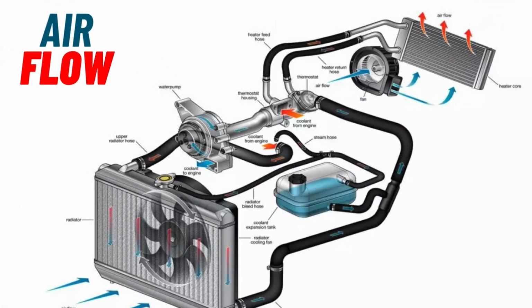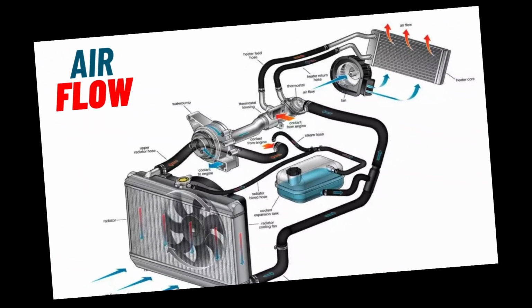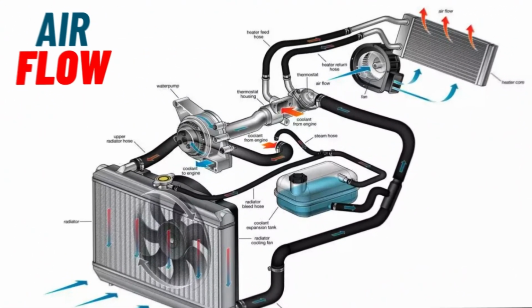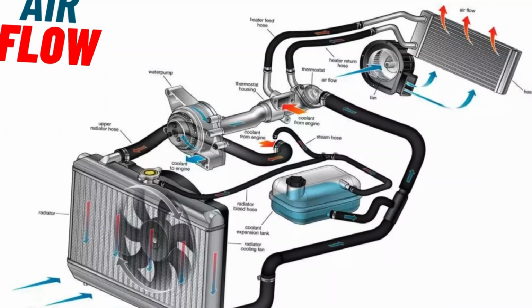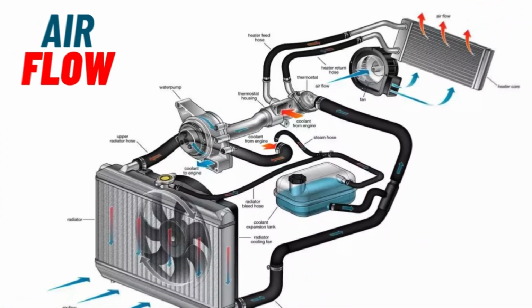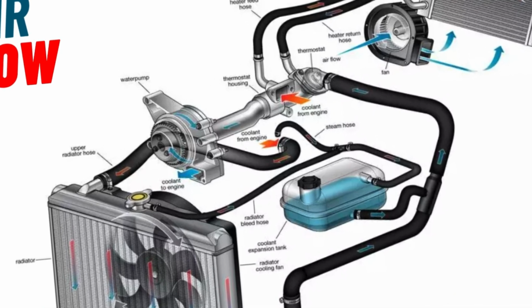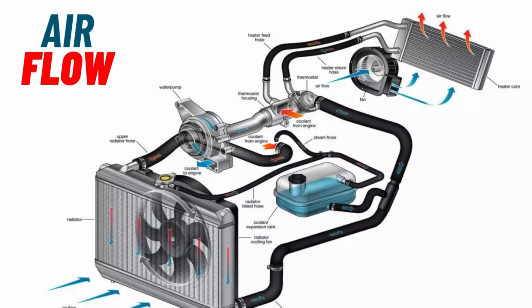Air flows over the radiator fins, either through the vehicle's movement or with the aid of cooling fans. This airflow removes heat from the radiator fins, cooling the coolant. The cooled coolant is then pumped back into the engine to absorb more heat, completing the cycle. This continuous process ensures the engine remains within a safe temperature range, preventing overheating and maintaining efficient engine performance.